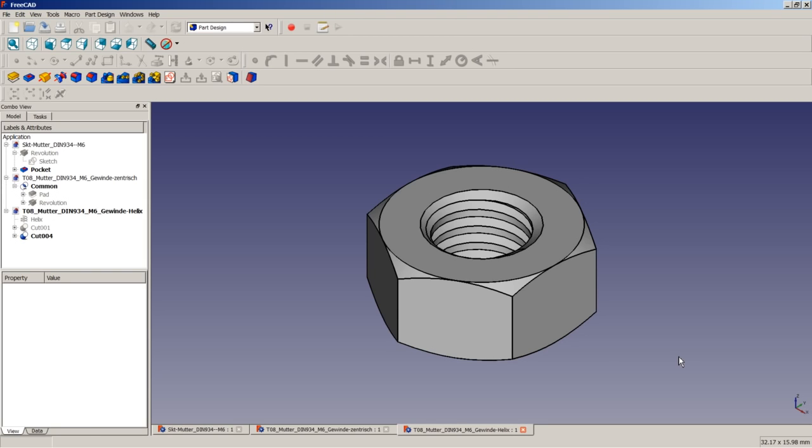When it comes to mechanical engineering, and we have, let's say, a quite complex technical machine of some sort, we have a lot of nuts and inner threads on all parts. But in most cases, you won't see the threads, because if you insert a bolt or a screw or something alike, the thread becomes invisible to you. To save CPU performance, in mechanical engineering, we don't use a representation which shows an inner thread.